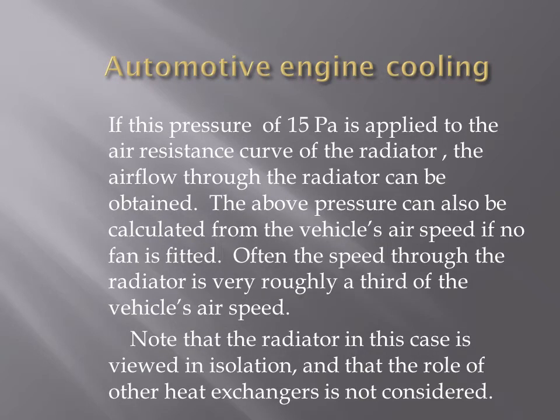If this pressure of 15 Pascal is applied to the air resistance curve of the radiator, the airflow through the radiator can be obtained. The above pressure can also be calculated from the vehicle's airspeed if no fan is fitted. Often the speed through the radiator is very roughly a third of the vehicle's airspeed. Note that the radiator in this case is viewed in isolation and that the role of other heat exchangers is not considered.